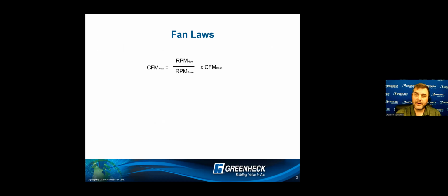The fan curves are our graphical language that we can talk back and forth and be on the same page and understand each other when we're trying to convey the performance point chosen versus its capability at different points of operation. But all this really boils down to, in the beginning, just understanding the fan laws, also known as the affinity laws. And of course, we have law number one.